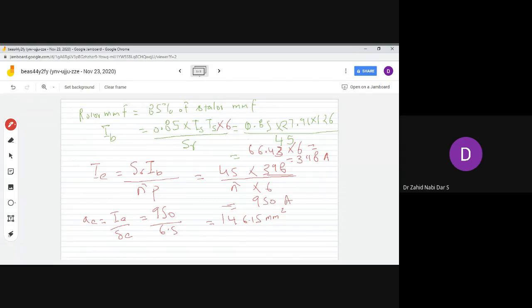So directly what you do is, first of all, in order to go for that, total copper I square R loss, you have to write SR, then IB square, that is I square, then R. For R, what you have to write? R is equal to rho L by A. Okay, R is equal to resistivity into length divided by area. So for resistance you can write: rho value they have mentioned, length also mentioned, area of the bar also, 11 into 6.4 millimeter, it's mentioned. Rho is mentioned as 0.021.